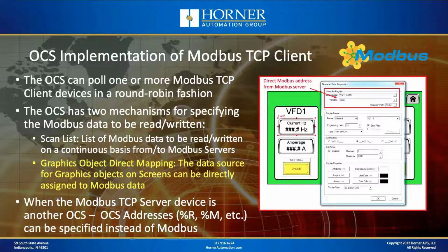But you also have the option from the screen editor itself to go into an individual graphics object on the screen and directly map its data source, not from internal OCS memory, but from the external Modbus server.